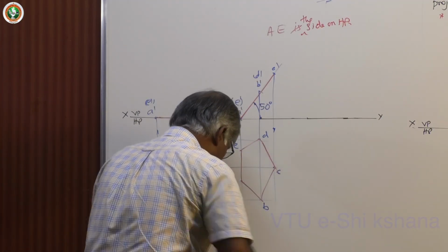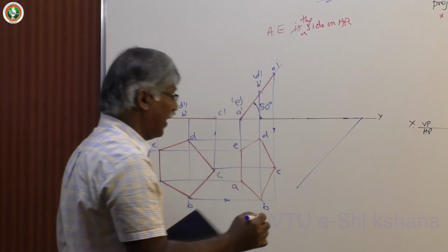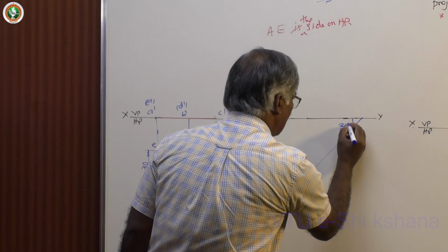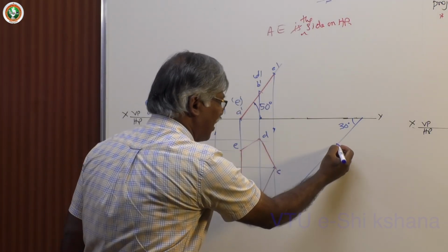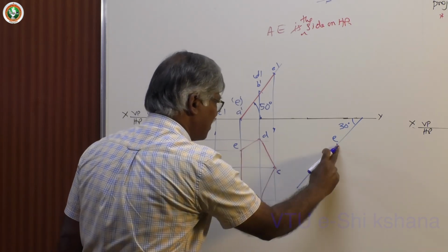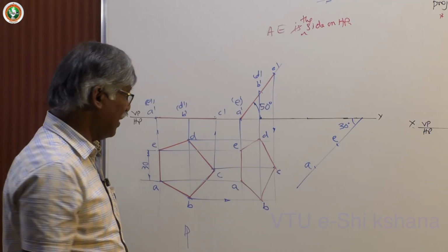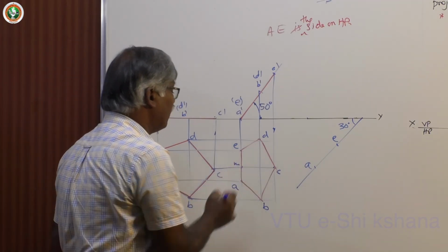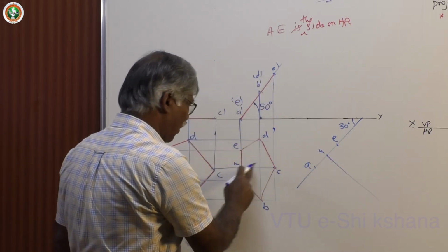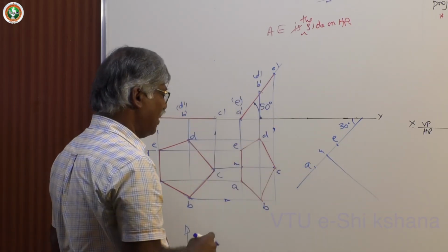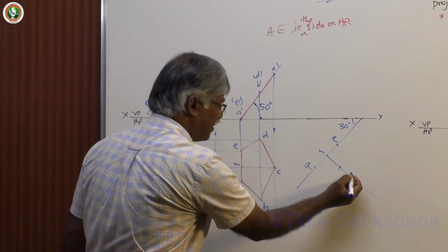By default, you take AE as the reference. I will draw 30 degree line. Keep EA first. Take sufficient length E. Then measure this distance, mark here, this is A. Then very easy to draw manually. Then let me assume this is M for construction purpose. Then draw perpendicular that houses one more point C here. Then take this distance and this, that's all.